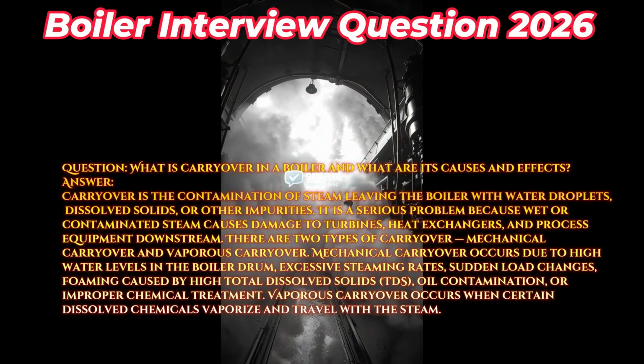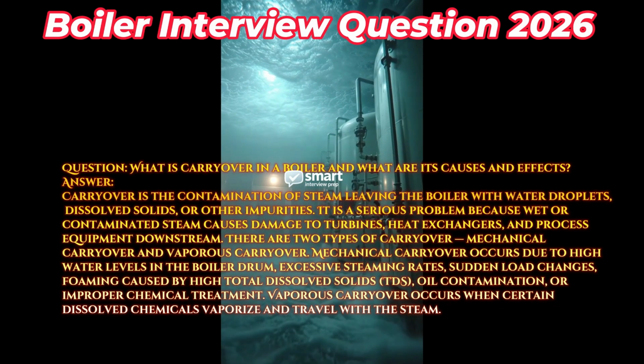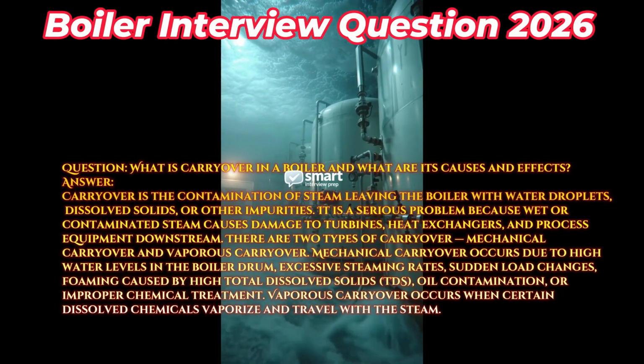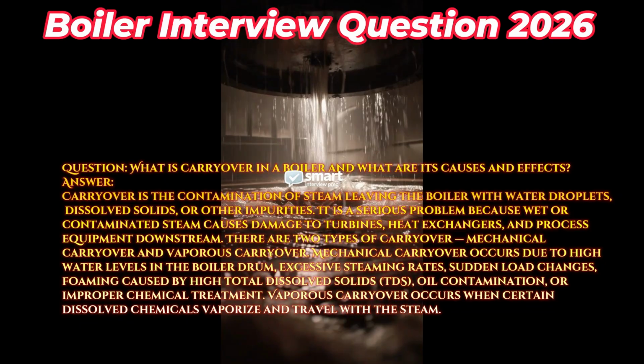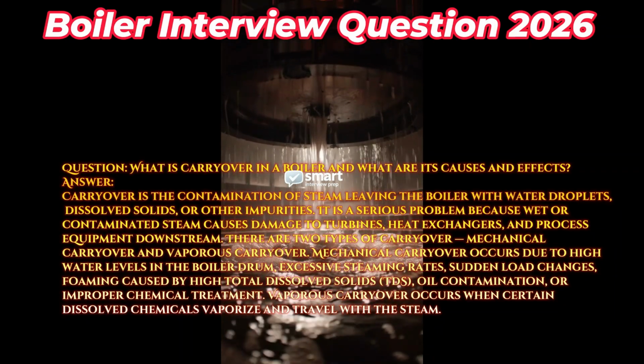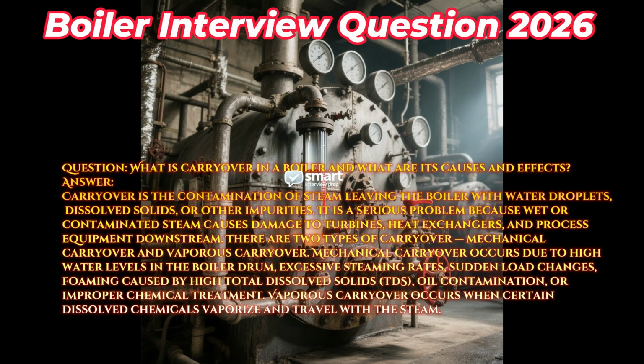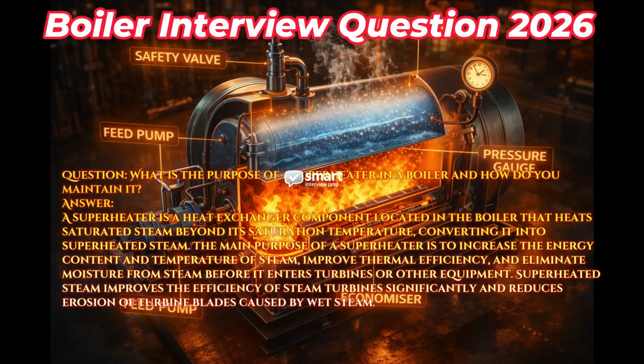Mechanical carryover occurs due to high water levels in the boiler drum, excessive steaming rates, sudden load changes, foaming caused by high total dissolved solids, TDS, oil contamination, or improper chemical treatment. Vaporous carryover occurs when certain dissolved chemicals vaporize and travel with the steam. Question. What is the purpose of a superheater in a boiler and how do you maintain it?